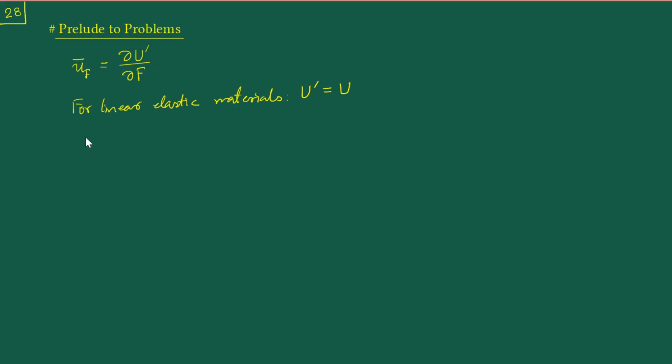But even before that, even if we want to use a linear elastic material where we can use the strain energy U directly, we have to be a little bit careful in the usage. Towards that end, you first note that this U is equal to the integration of the strain energy density, which is per volume, like this. All that is fine, but what exactly is the form of the U that we should be using, especially when we are interested in solving beam problems?